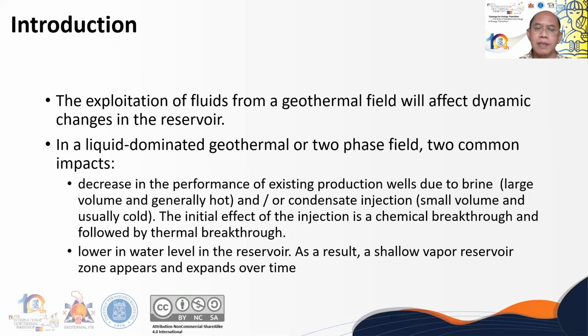The first one is a decrease in the performance of the producer, which experiences injection effect, named chemical breakthrough, or in the long period, thermal breakthrough. And the second impact, because of exploitation, is a lowering of the water level in the reservoir. As a result, a shallow steam reservoir appears and expands over time.